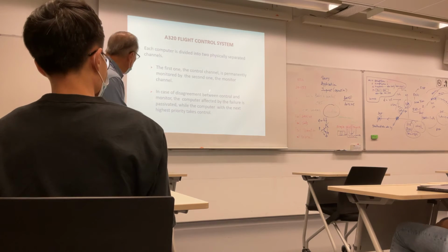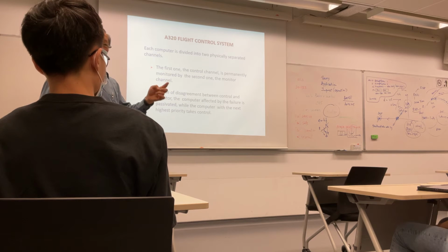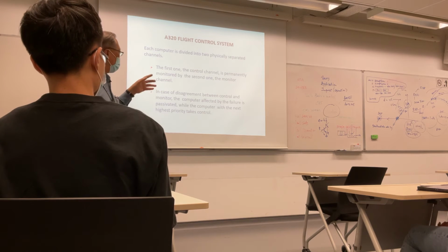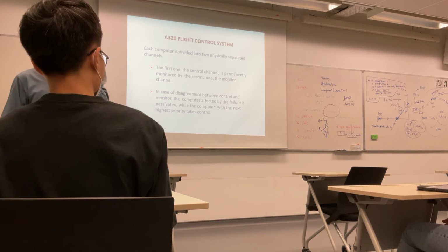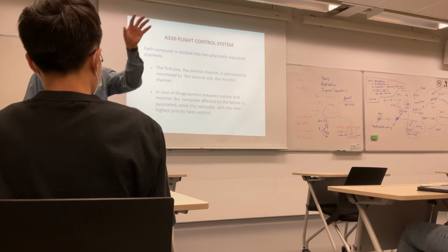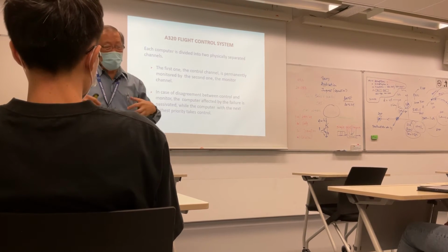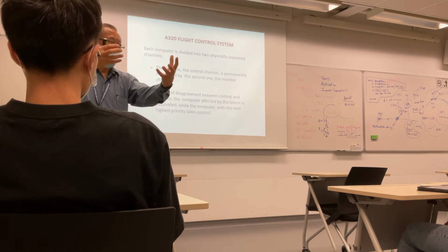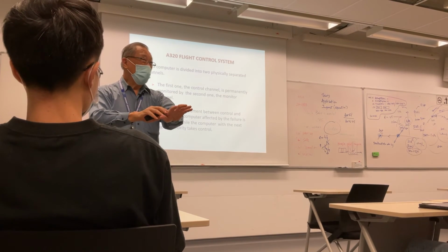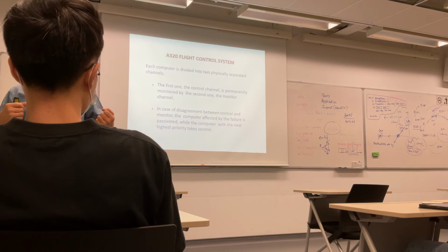Now further, if you have multiple channels, you have to do fail passive. That means the failed channel should not interfere with the working channel. I'll give you an example of how a fail passive system fails. You know the BAC-111 aircraft, where the pilot got sucked out of the cabin? The windows used lock screws. When the pilot was sucked out of the window, his whole body was pushing the control column down. So the guy, when he got the problem, is causing the other pilot to fight against it.